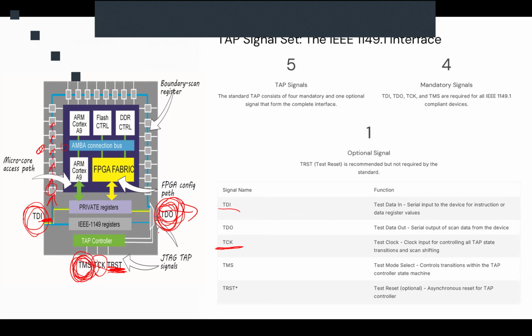Now, for example, let's say we have a defect here, where this cell is short-circuited to the ground. What's going to happen? We send several vectors into that boundary scanned system and we measure the output. When we measure the output, we see that no matter what the input is, we always capture a zero value on this cell.